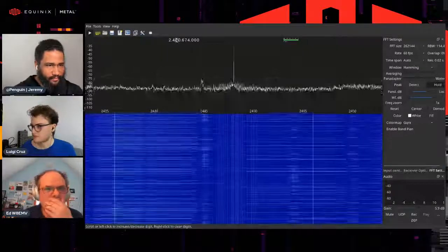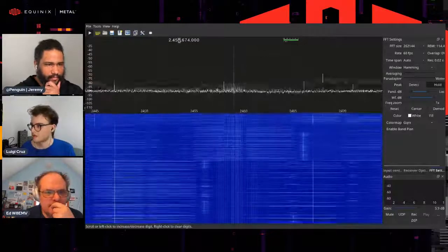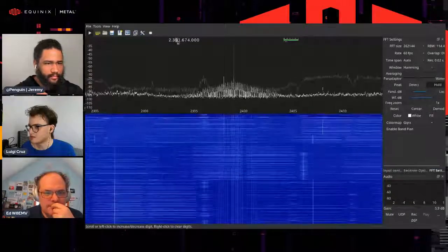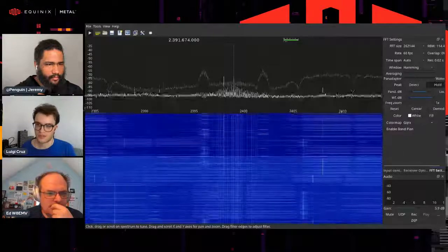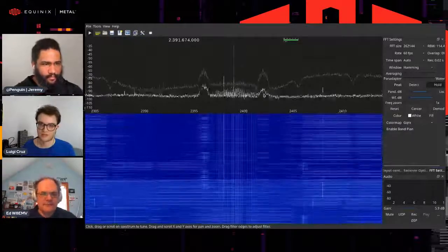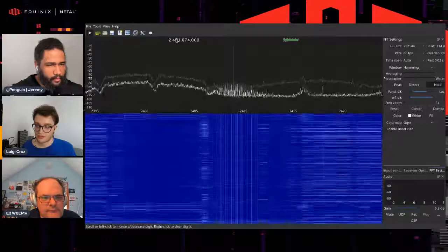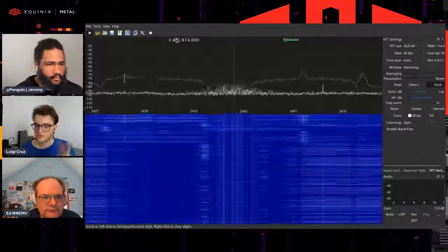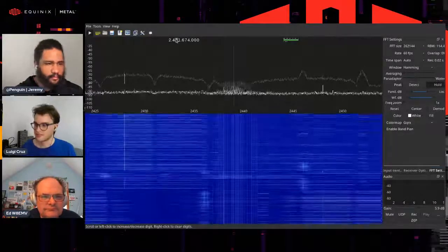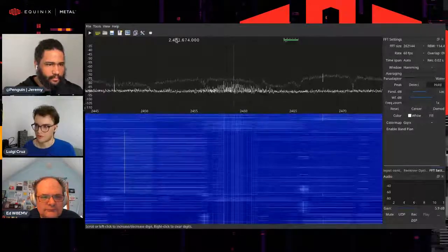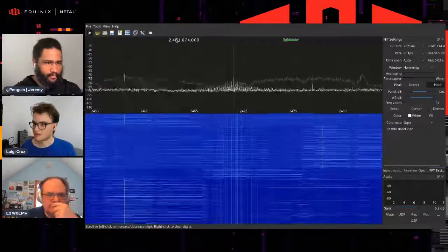And you can see some interference here with some networks talking on top of others, and other tiny signals. These tiny signals here can be Bluetooth or other types of transmitters, like mouse and keyboard transmitters, that use a narrowband signal. So 2.4 is an open frequency that almost any device with proper certification can transmit on.